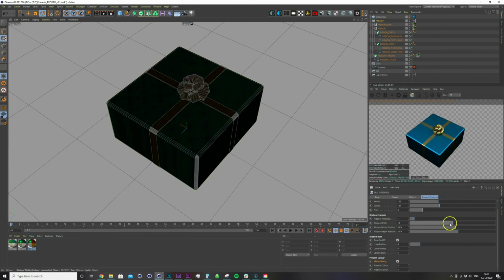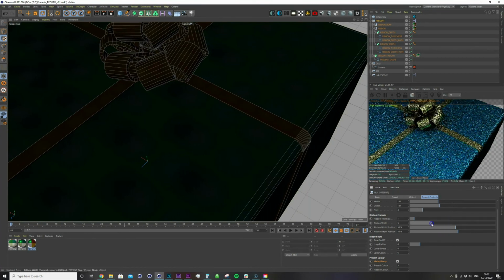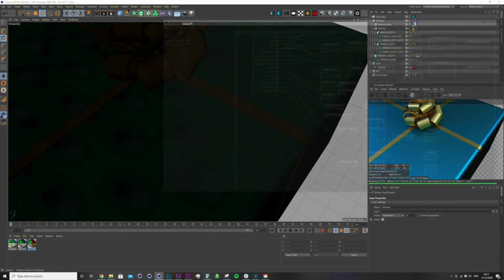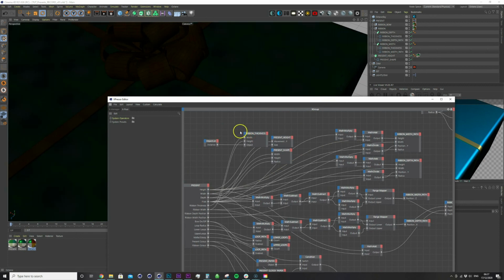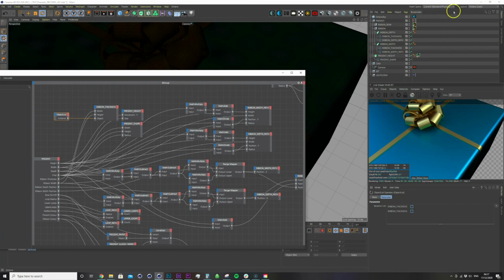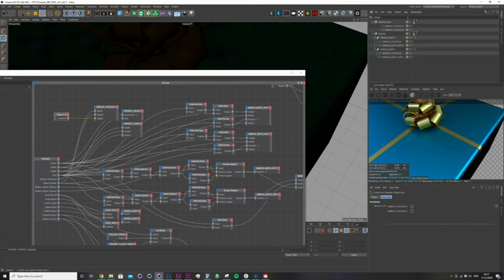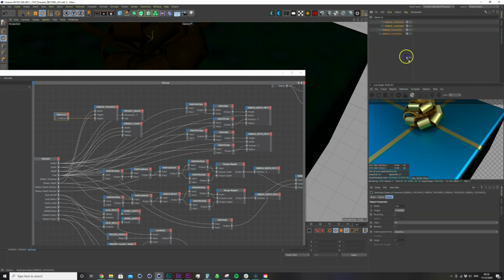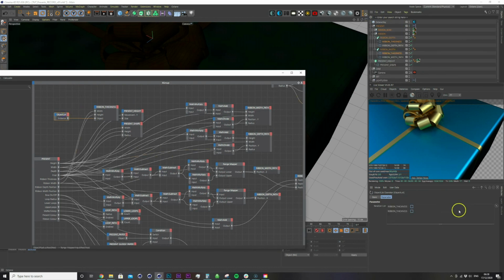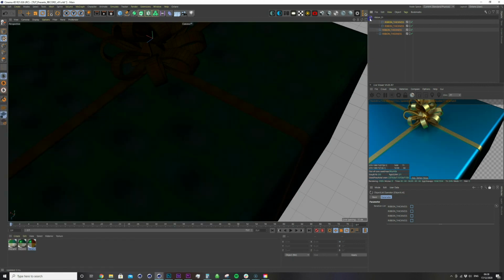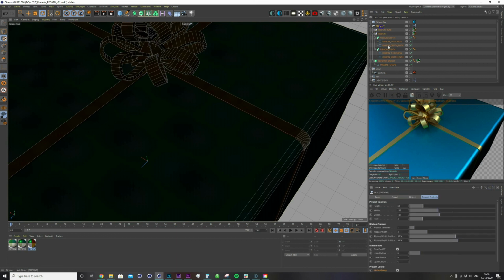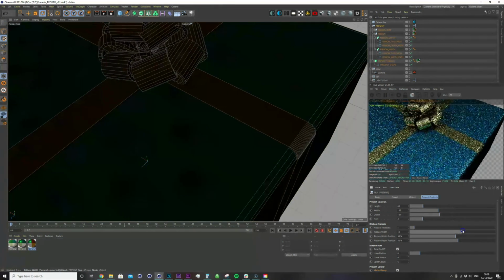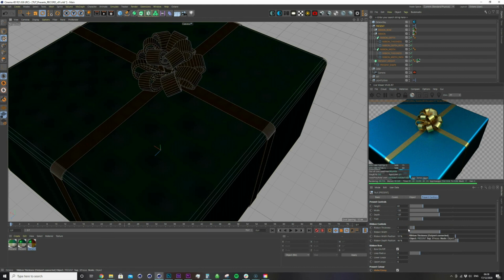Okay, and we do a spot of troubleshooting, we immediately see this problem. Okay, as in the ribbon thickness here does not correspond to what's going on here. So that is a very easy fix because we adjusted it that way earlier. If we go with ribbon thickness, we know that we can lock this and drag all of these in there. And now we'll reach the same thickness, or the same width rather.